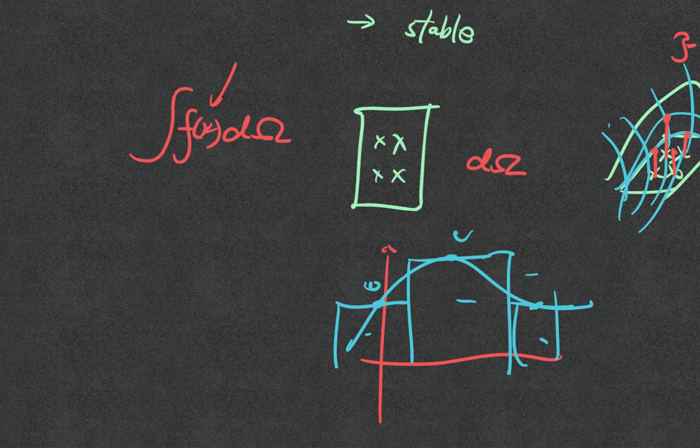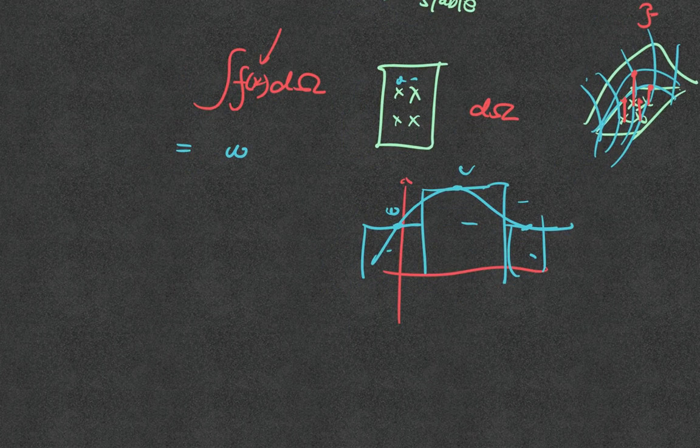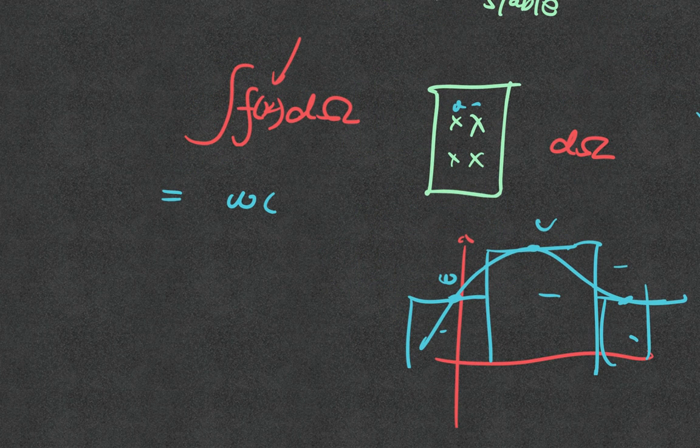To do that, if you assume a polynomial, you can find out the coefficient W, and this integration from your finite element, you probably already learned, is going to be the weight of the function at that particular Gaussian point times the function value at that Gaussian point. This is called the Gaussian point.